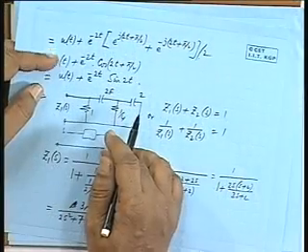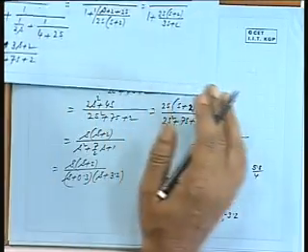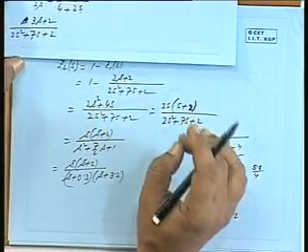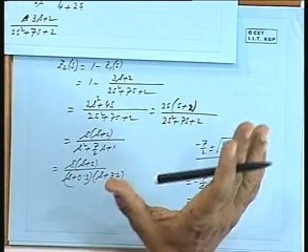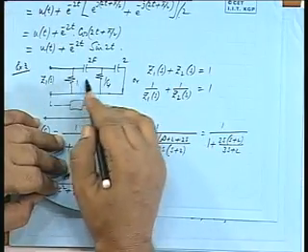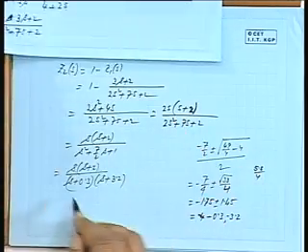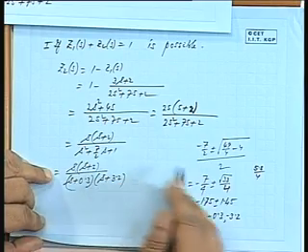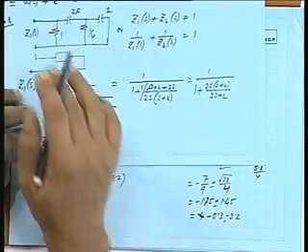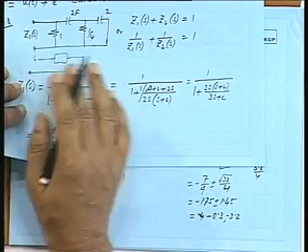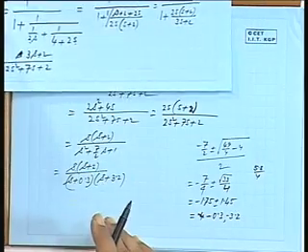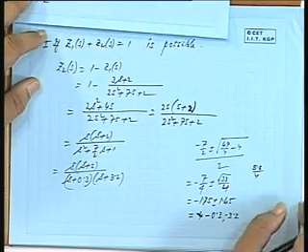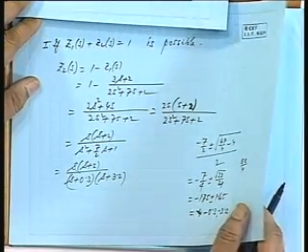An RC network will always give you some R minus jX form, then the other one has to be R plus jX form. Any RL circuit you take, series, parallel, all that, for any frequency omega, its net value will be R plus jX. So if this is R minus jX form, this one has to be R plus jX. So this is possible. Now you can realize this. I leave it to you as a simple exercise. You can find a Foster 1, Foster 2, Cauer 1, Cauer 2, any of them to realize this. Let us see the other possibility.